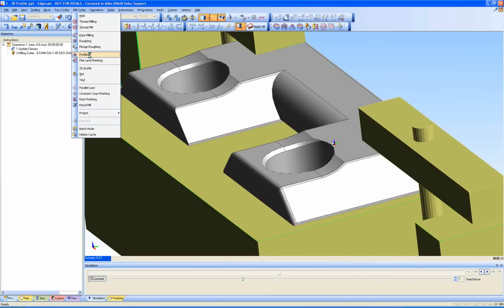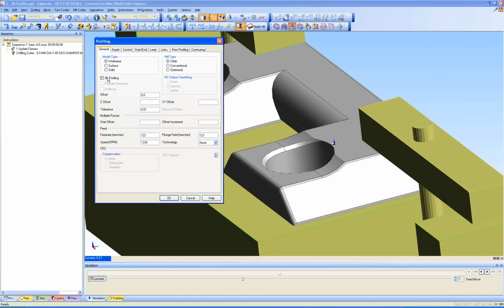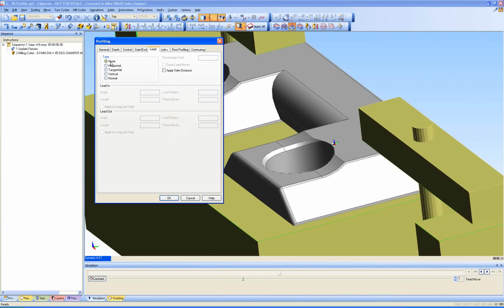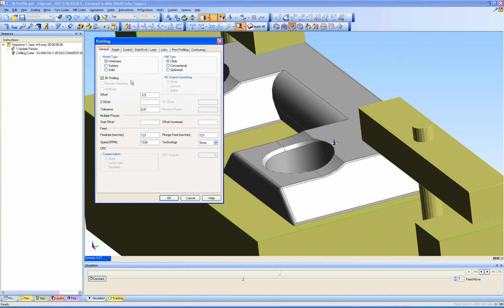And in a profiling command we say on a wireframe using 3D profile, I'll push the offset into negative. You can't go larger than the radius of the cutter. I will be warned about that. And then obviously just populating sizes that suit this particular machining condition. As I'm filling these in, obviously this makes a very good justification for a PCI, rather than having to remember all the fields in the dialog. Use it as a PCI, and it really emphasizes what we said in the first demonstration with review.